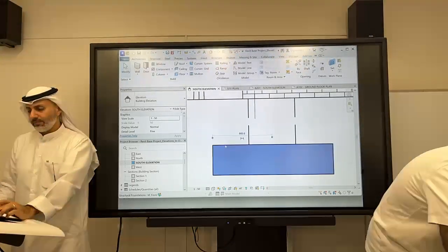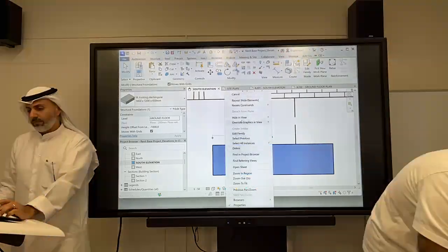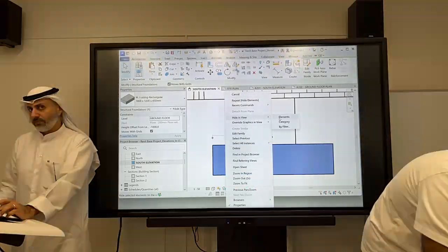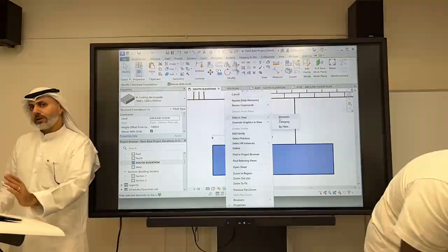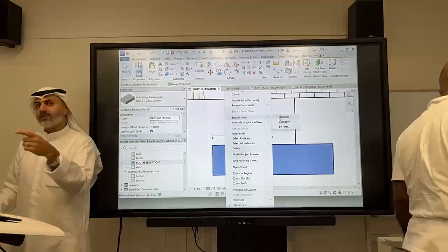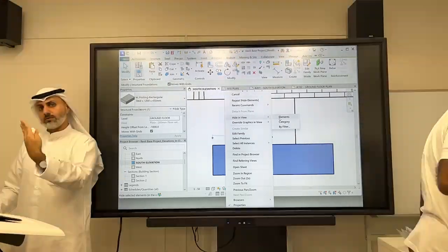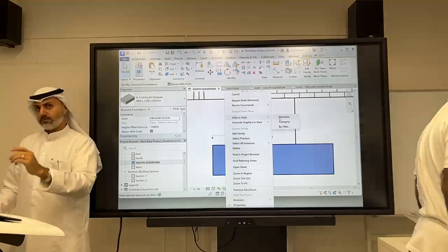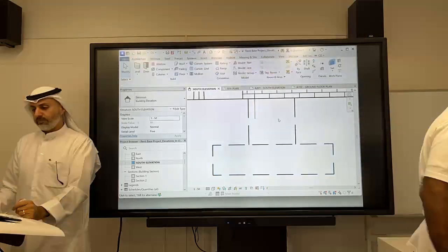It's cutting. Each floor plan is a section cut. You're probably looking at the column from the 20 cm side, not the 80 cm side. Adjust the cut plane so I can see the openings. And that's usually through view range.